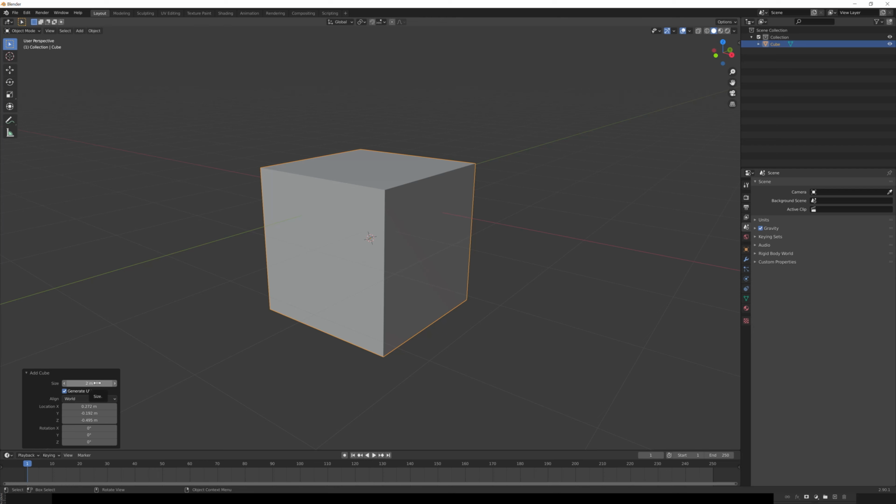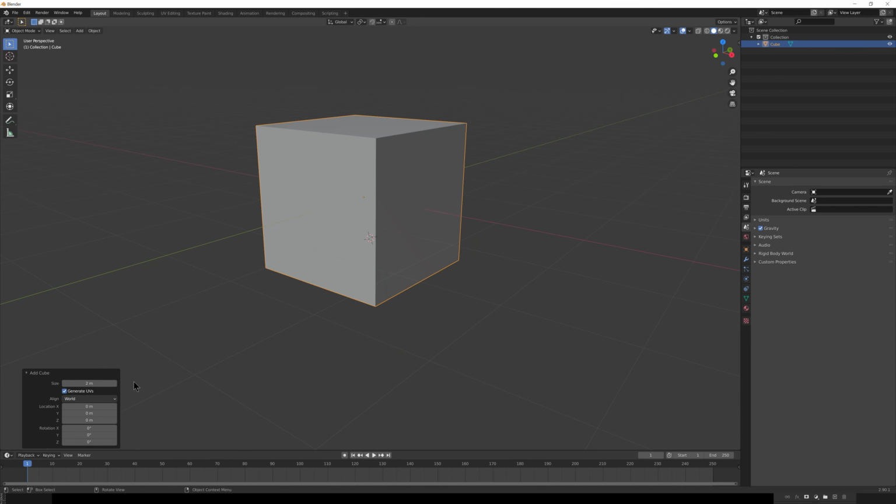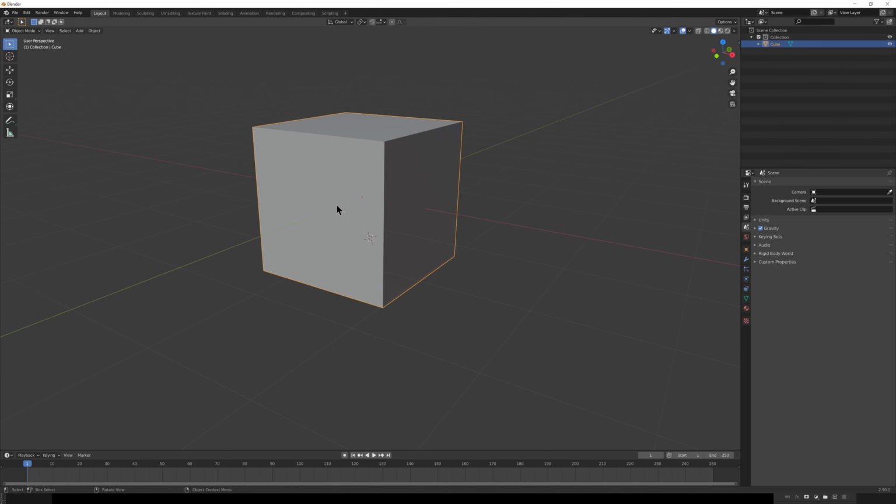That's a bit large for what we want, but I'm going to use the scale tool instead of these interactive ones over here. However, one thing I will do is go ahead and click and drag on those different boxes and hit 0 for all 3, so that it's back at the origin or center of my world. The orange dot is, of course, the origin for that object, its local space, or pivot as it's referred to in many other applications. We will want to make sure that pivot is in the correct place before we export so that it's easy and convenient for us to sandwich this wall against other objects.